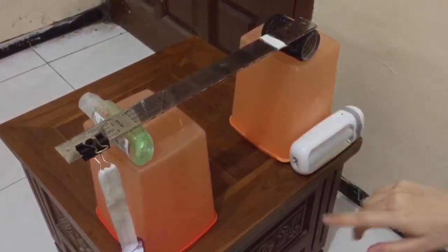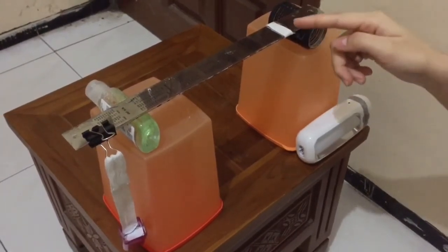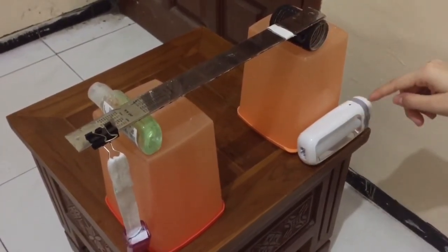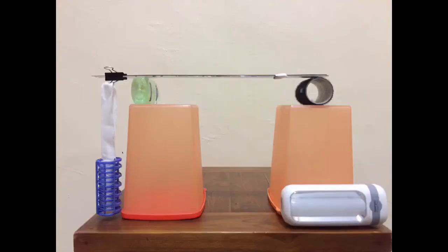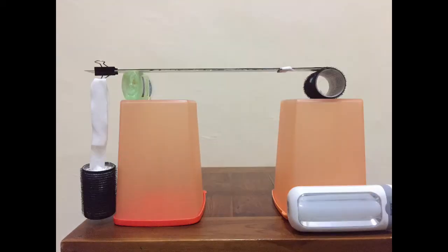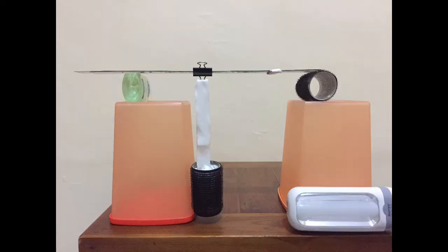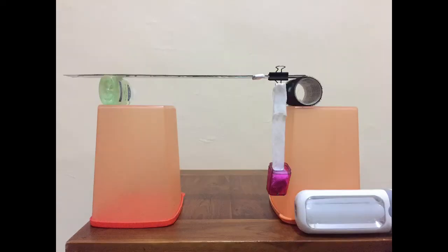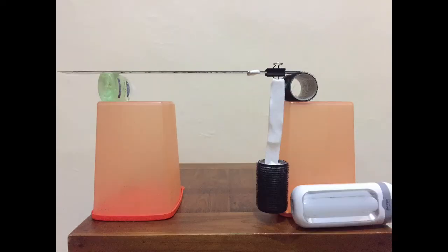After that, the display meter here will show you the shear force at this section, at XX section, and the value we will record on our laboratory sheet after multiplying it with -1. The experiment is repeated by increasing the load to 200 gram and 300 gram of mass and moving the loads to 140 mm and 380 mm from point B. The same principle is applied to conduct the experiment of shear forces due to UDL and superposition.